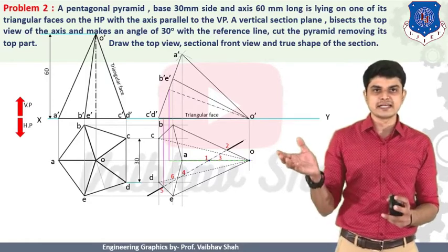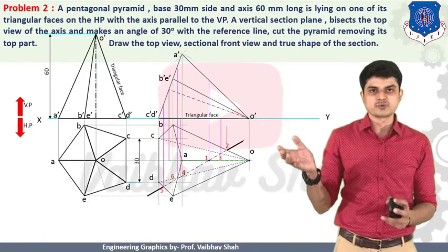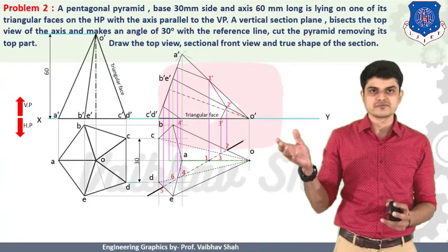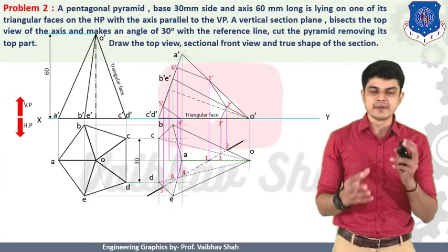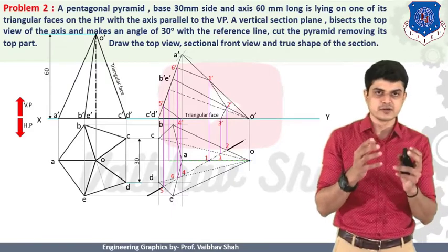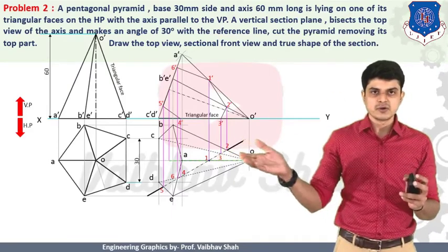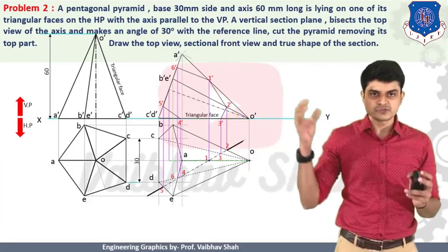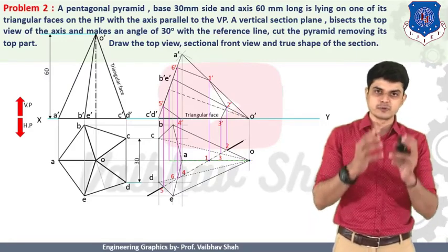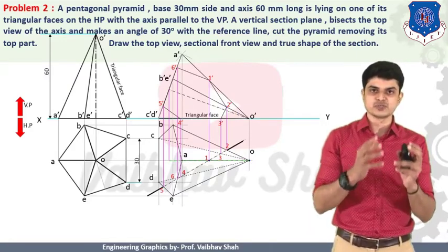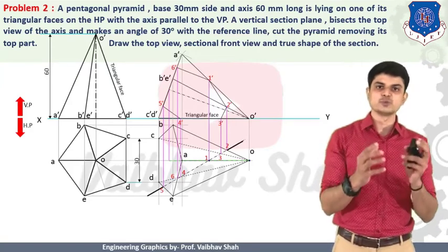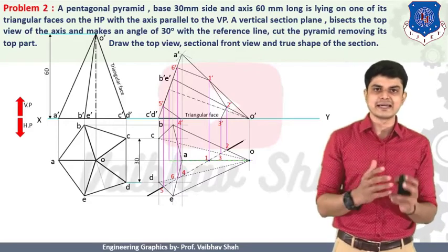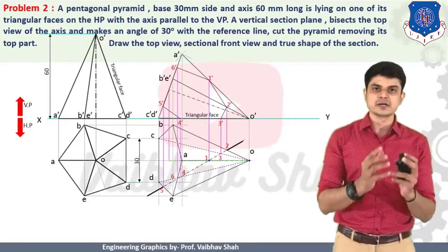And after transferring each and every point to the corresponding lines, we should join these points, and we should give the numbering like this: 1 dash, 2 dash, 3 dash, 4 dash, 5 dash and 6 dash. So we will be able to complete the object generated. So let us observe, we have transferred this point 1 onto this OA line somewhere here. Then we have transferred this point 2 on the OB line somewhere there. So we should transfer each of the points vertically up to the corresponding line. And after getting these points, we should locate them as 1 dash, 2 dash, 3 dash, 4 dash, 5 dash and 6 dash. And then we should connect all these points by a darker line, and we have this cut section generated, which is nothing but our final.